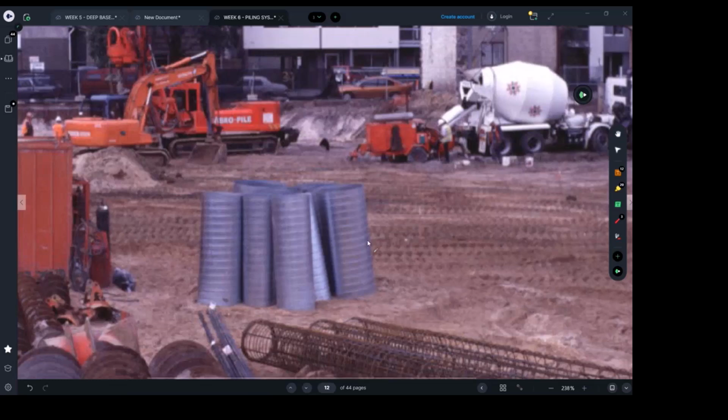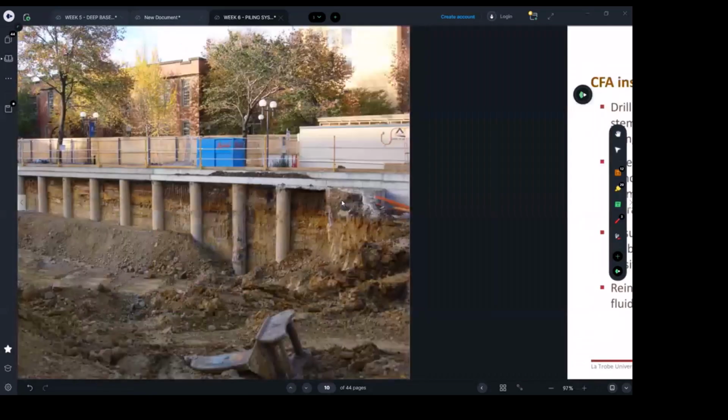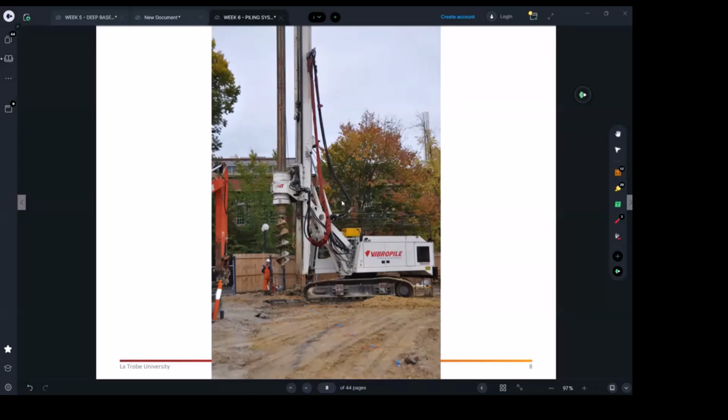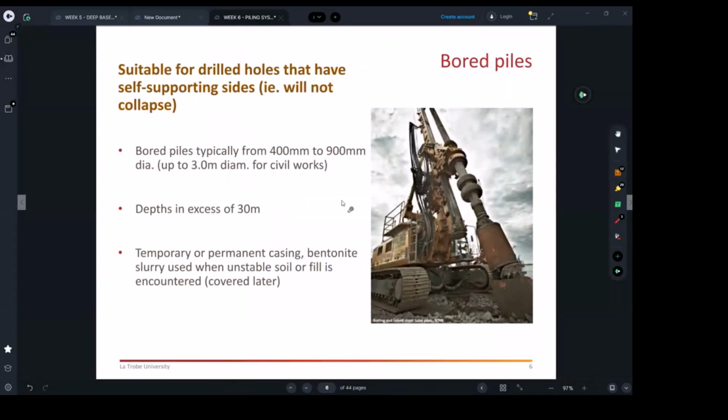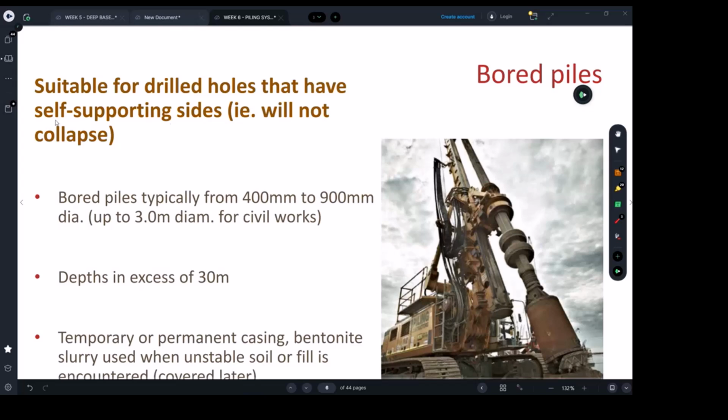But usually we can go with those ones, the ones you're mentioning, if we have only 3 meters excavations and the soil is really stable. You still can use this all the way down to the bottom, but you have to make sure it is self-supporting soil. As I said to you, we're talking about large construction sites, large developments, which we're trying to cover in this project, and the type of examples I'm showing you.